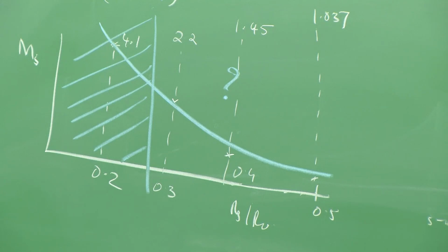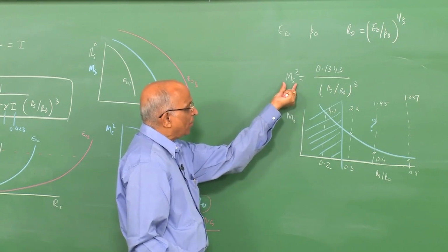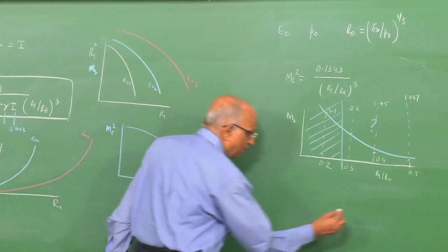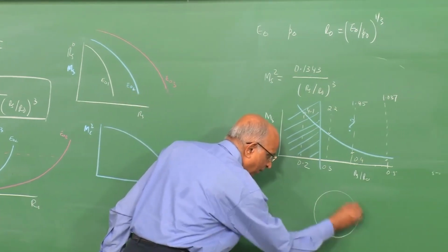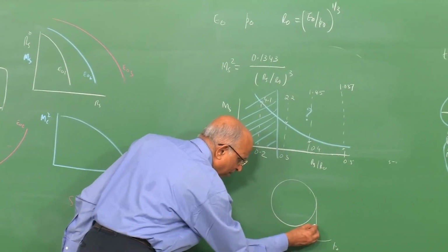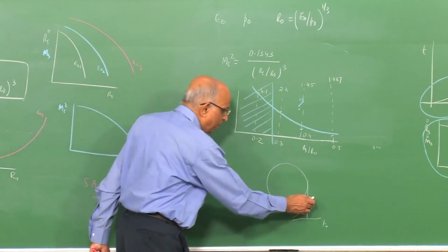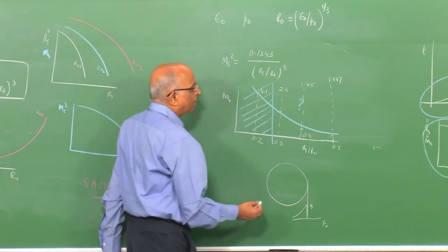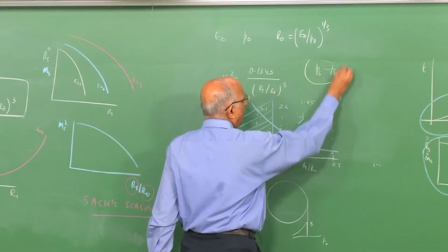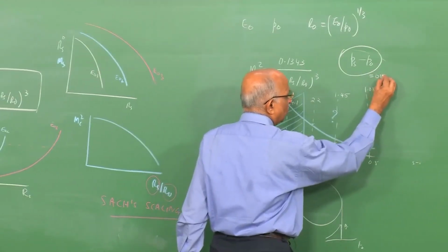Therefore, what have we done? Using energy balance, we are able to get the lead shock Mach number, and if I get the value of Ms square, I will be in a position to get my pressure also. When the shock is propagating away, at the lead shock the initial pressure is P0, there is a jump in pressure to a value Ps, and then it decays further. The jump in pressure is Ps, the initial pressure is P naught, and Ps by P naught is the increase in pressure across a lead shock wave, and this is known as overpressure.